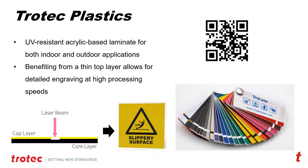And the way that it works, here in the lower left-hand corner, the cap layer is a very, very thin cap layer. The laser beam ablates or vaporizes that cap layer and exposes the core layer. So you've got a thick core and a thin cap, and then the laser engraves away that cap layer, exposing the core, producing the contrast. These are typically an acrylic-based product, and so there are indoor versions of it as well as outdoor versions. Here's a QR code in the corner if you want to scan this QR code and be taken to our webpage that will explain a little bit more details on this.